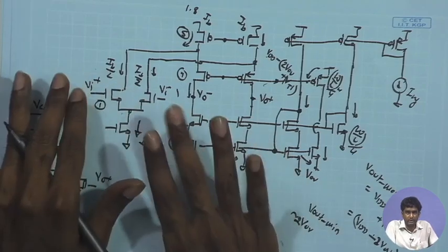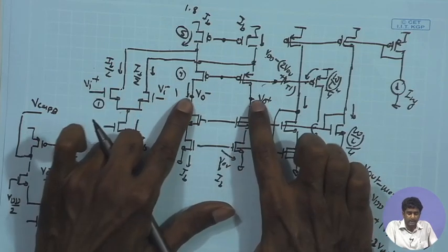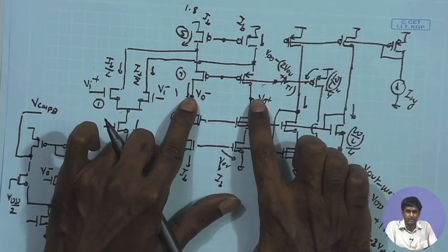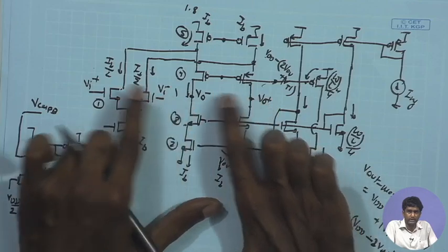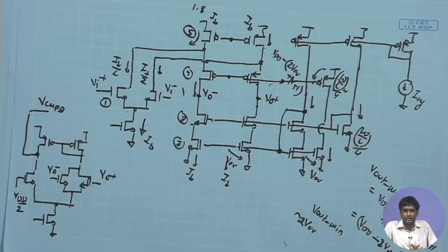But in the case of folded cascode, the output DC potential over here is not directly impacting the input swing over here, and therefore, it is convenient to directly connect the output DC potential to the input DC potential. So, we do not need any high resistance to disconnect the output and the input of the input pair to self bias.